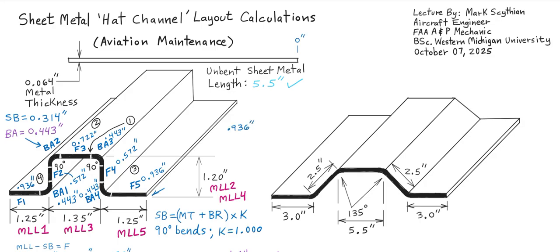So we can zero out the right side here on the sheet metal section. So maybe your brake is right here and you'll start feeding it in on the right side. All that the brake is doing is putting these controlled bend allowances in without cracks or stress risers. So that's why you need the sheet metal brake.